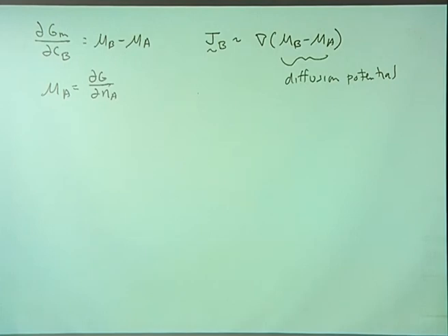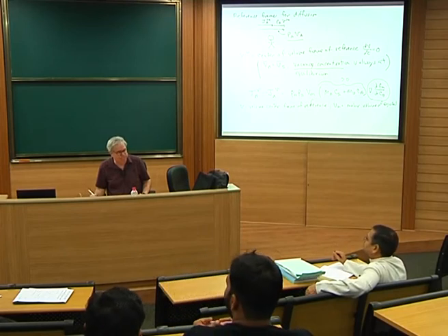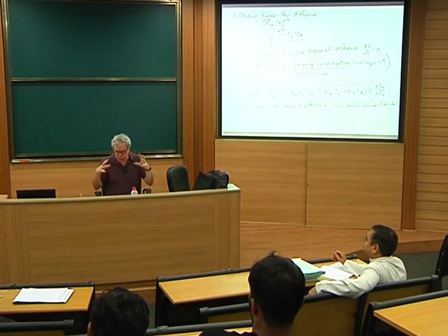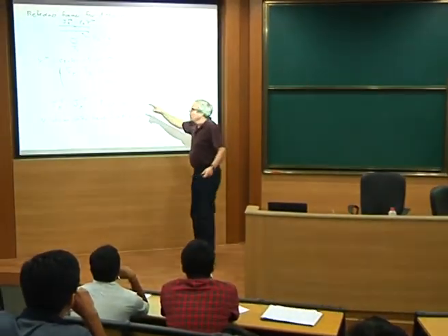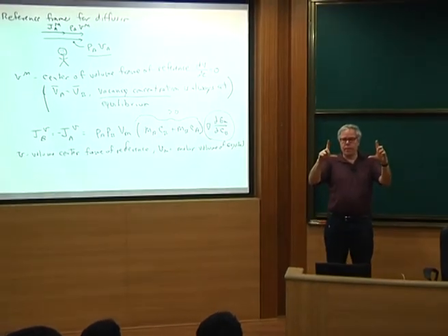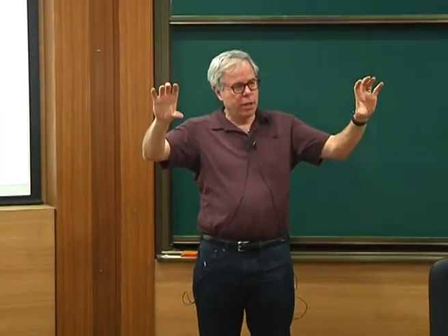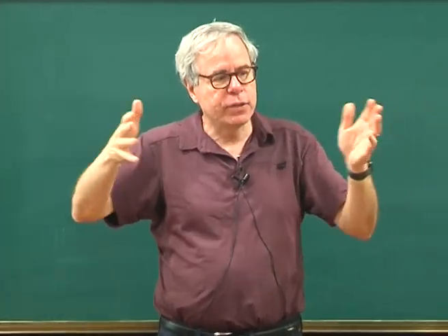Oh yeah, sorry. We have a good vacancy concentration at equilibrium, that's clear. But why the molar volume? Yeah. If you're in the center of volume frame, one of the assumptions this equation makes, to get to here, is that as A and B interchange, the volume of the bar doesn't change. In other words, you don't get fluxes due to the volume changing. If you did, you'd get a different equation here.